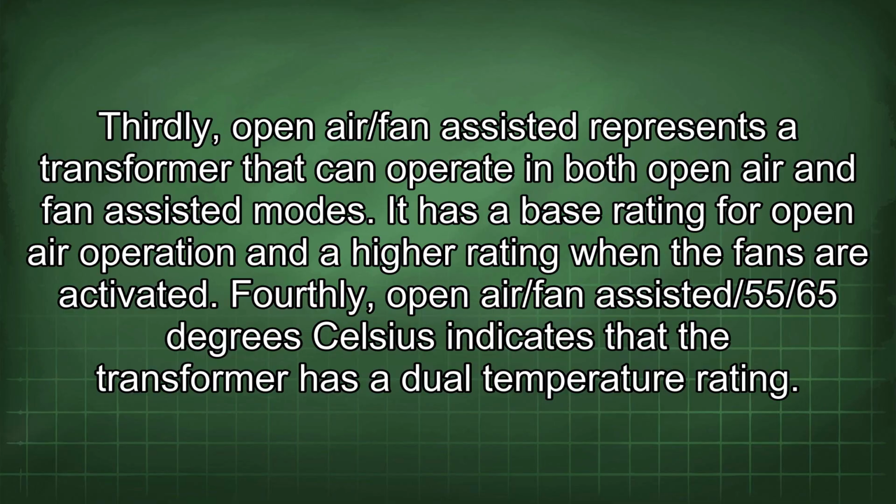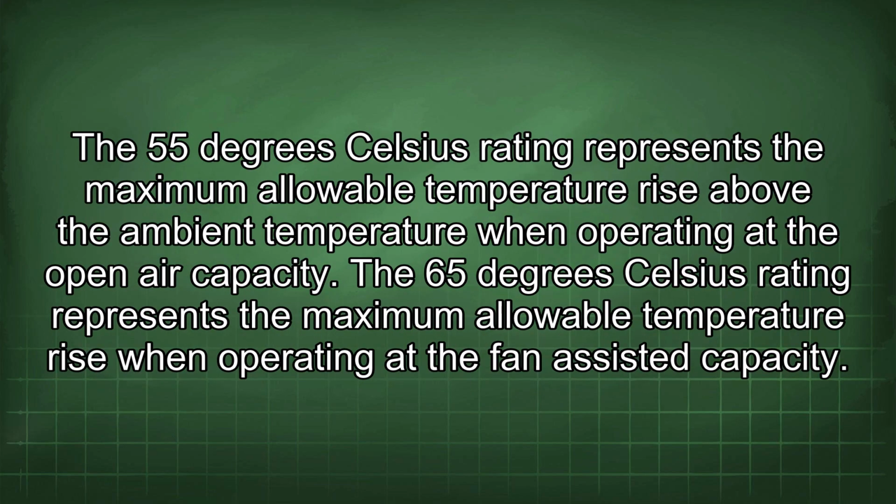Fourthly, open-air/fan-assisted/55/65 degrees Celsius indicates that the transformer has a dual temperature rating. The 55 degrees Celsius rating represents the maximum allowable temperature rise above the ambient temperature when operating at the open-air capacity. The 65 degrees Celsius rating represents the maximum allowable temperature rise when operating at the fan-assisted capacity.